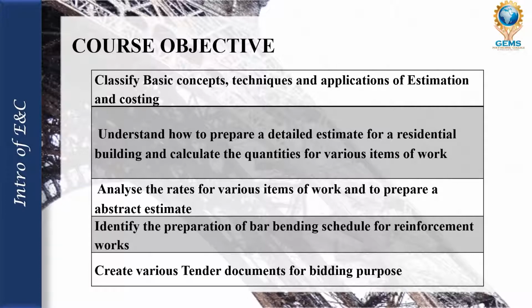Second, understand how to prepare a detailed estimate for a residential building and calculate the quantities for various items of work. A detailed estimate is the cost of all the activities and materials that would be used in finishing the project. It is a detailed description of the project.